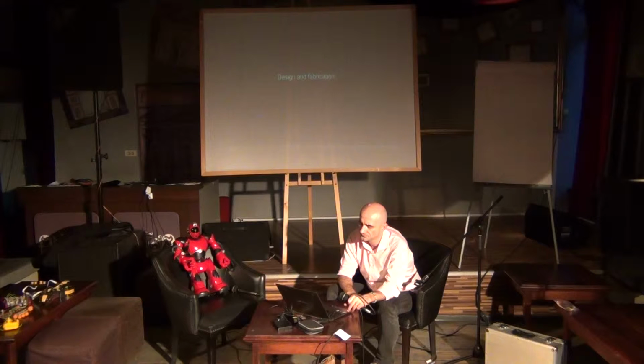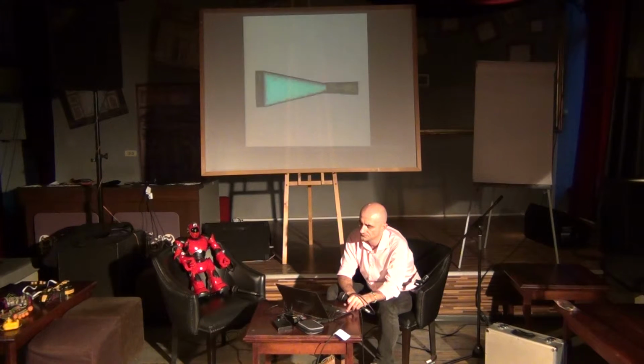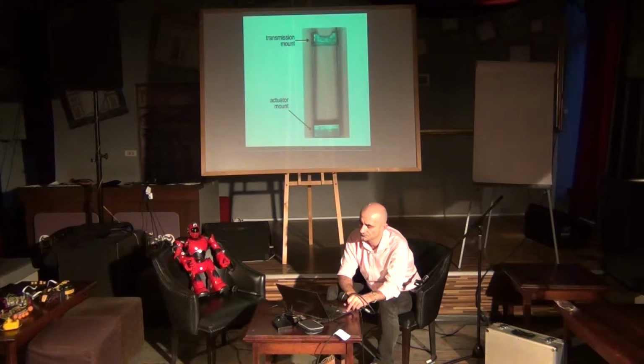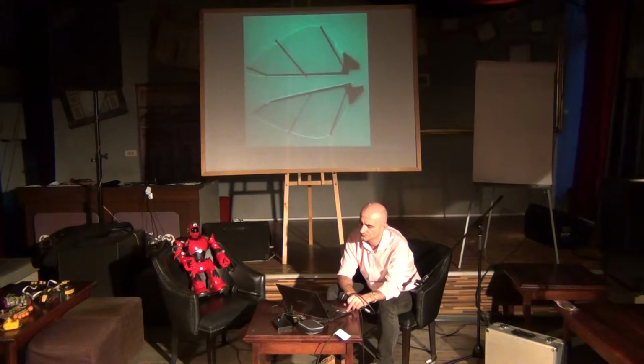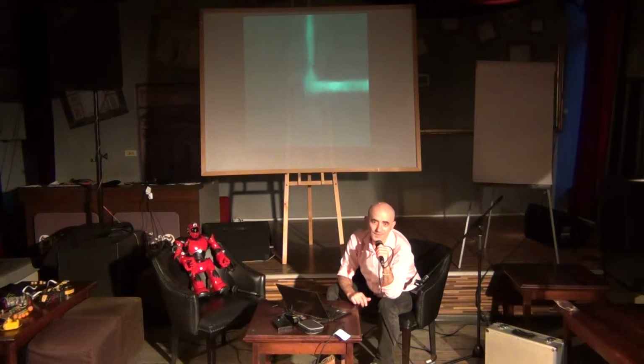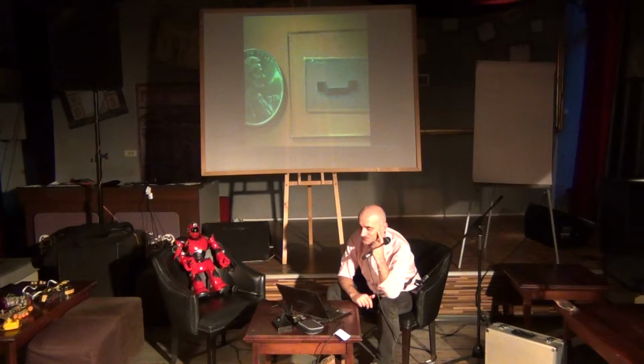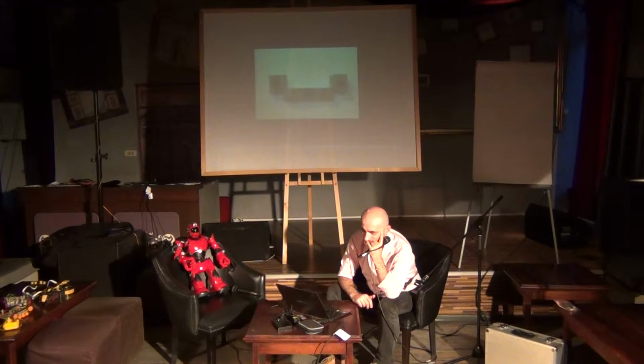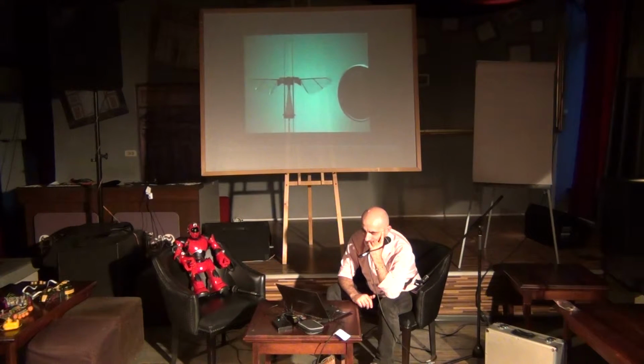There are 4 primary components to the mechanical system: the actuator, or flight muscle, transmission, or thorax, airframe, or exoskeleton, and the wings. Each is constructed using a mesoscale manufacturing paradigm called smart composite microstructures. This entails the use of laminated, laser micromachined materials stacked to achieve a desired compliance profile. This method is inexpensive, conceptually simple, and fast. For example, all the components of the fly can be created in less than 1 week.